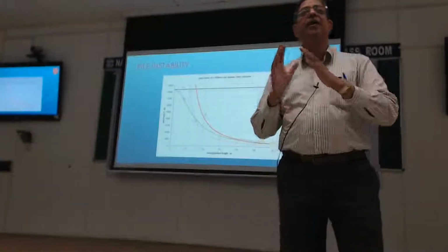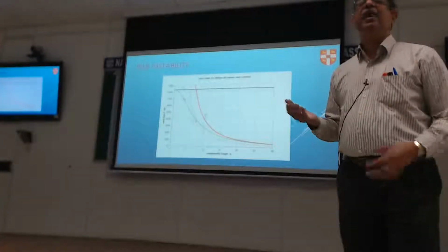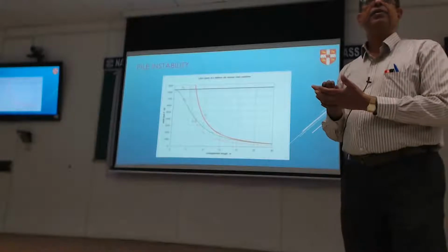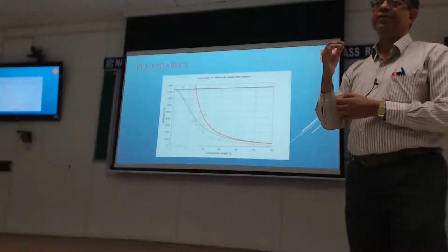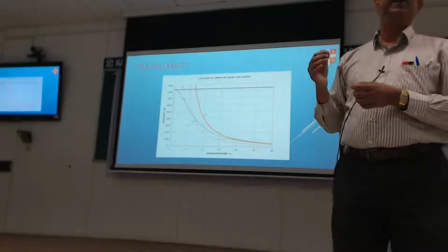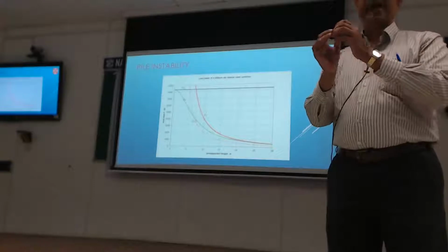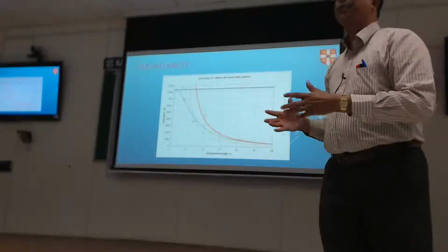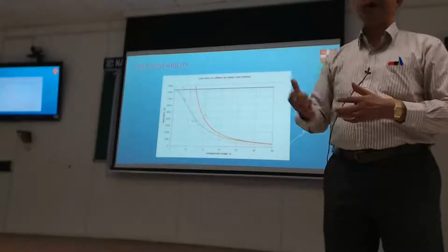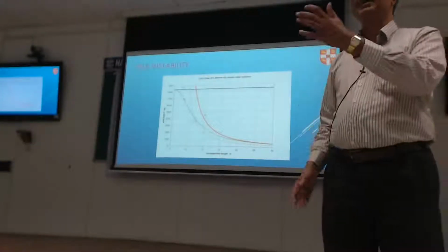When you do this buckling calculation using the Euler equation, it is very simple. It only ever worries about pure axial load. Now, everybody in construction knows that there's no such thing as pure axial load. Your loads always have some eccentricity. Your piles are never straight, either because of the pile boring or even columns are not that straight.